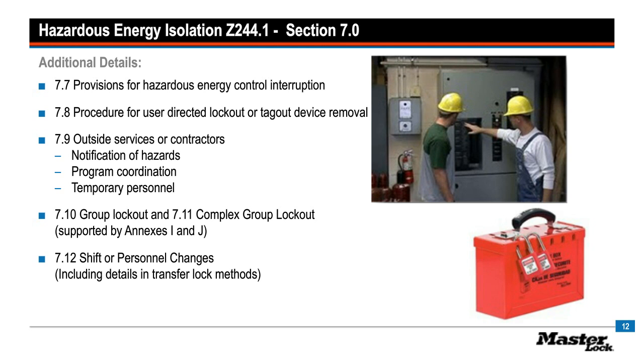One area that we noted involved a lot of lockout accidents involved outside services being brought in or contractors. And so an expansion of how-to methodology talks about a notification process to exchange information on hazards that the contractors may be exposed to or hazards that the contractors may create in doing their work that exposes facility workers to potential dangers.